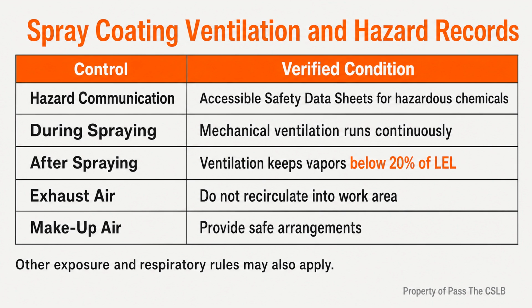I want to close the technical lesson with 4 decisions. First, treat California Green as mandatory code, not an optional certification. Second, match manufacturer information to the product actually used. Third, classify the product before comparing its number. Fourth, keep material compliance separate from hazard communication and spray safety. The central memory connection is still the shortest. The clipboard must match the can. If a proposed substitution breaks that match, stop before application and rebuild the verification chain.